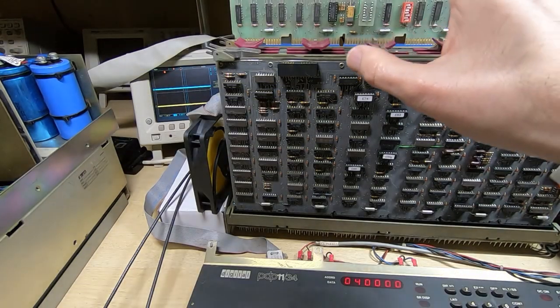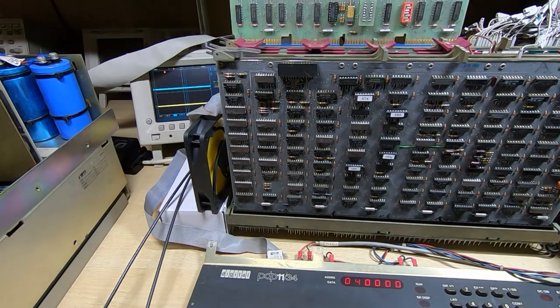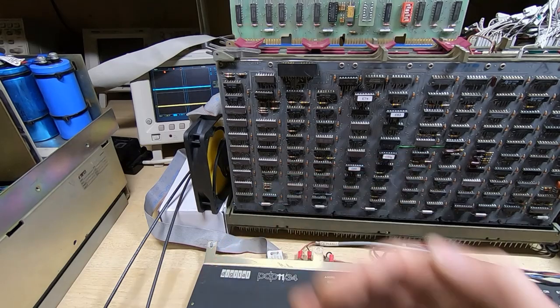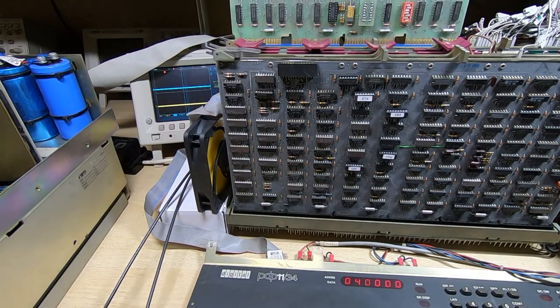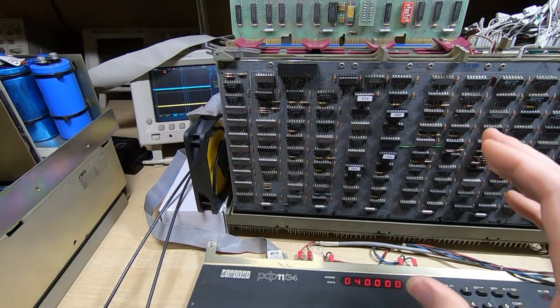The RX211 can then send the data through to the control CPU card in the drive. The control CPU card can successfully control the interface card, set the drive solenoid relay and drive the stepper. You can't see it, but I could see the drive stepper actually moving. It drives 1 track away, then back to the home position when you reset. I'll move the camera later on so you can see this moving. So we know quite a lot of this is working.